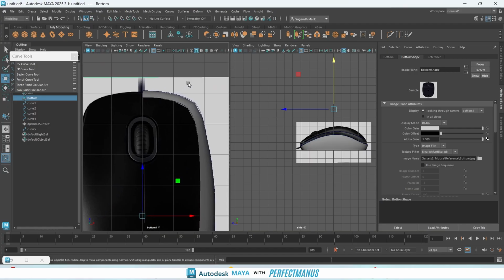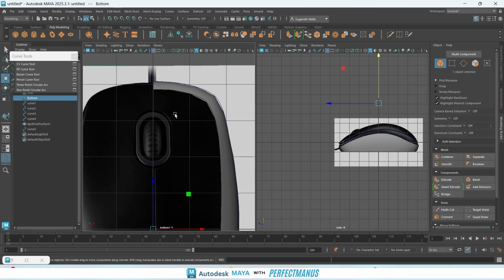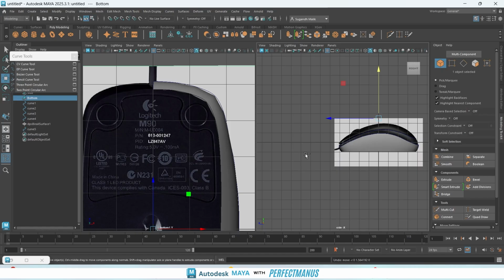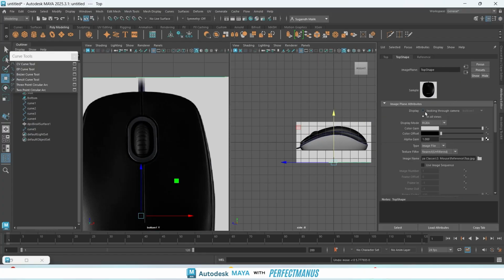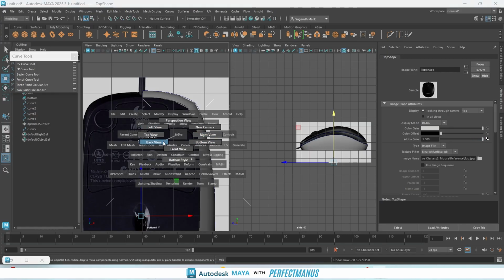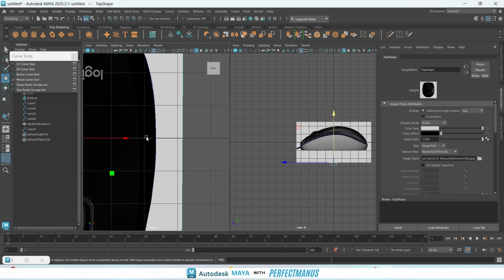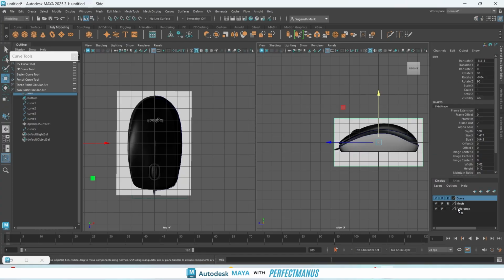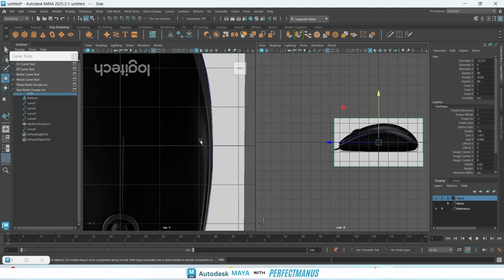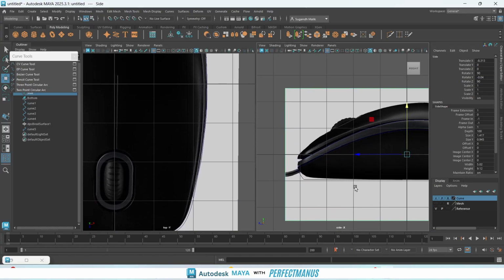Okay, now you don't need to see the mesh there. Mesh is getting in our way. It was harder for us to see. You can fix it by simply removing those from the view. In the top view you will see this. While you come in the top view, okay, that thick area, now I can understand what it is, this part. You don't need this one right now, your mesh, so simply disable its viewport. Now see, it's so much clearer.